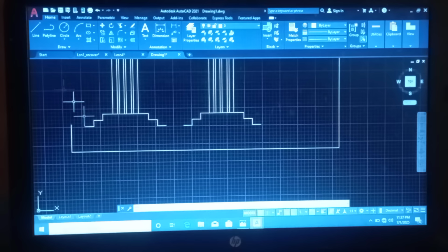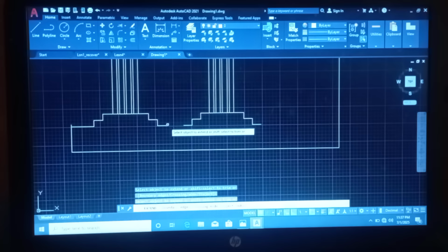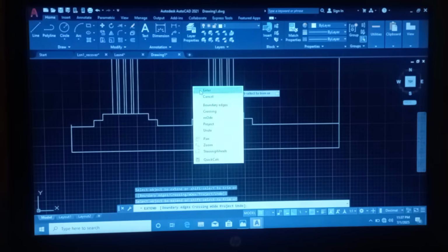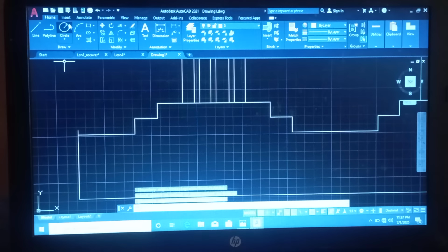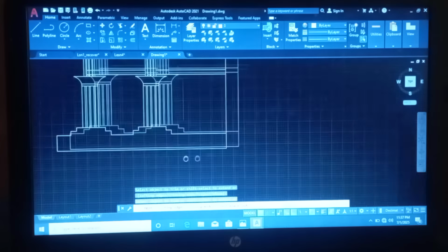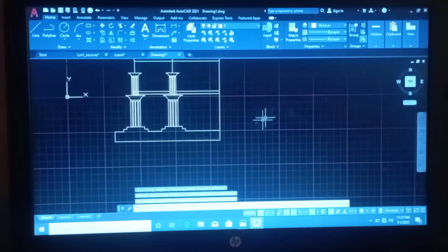There are many ways of going about it. Instead of taking line to come and draw, I come to modify, use extend. Watch what happened now. We extend it automatically. See what happened. Extending. Watch the left side, the right side. It extends and does that. So I'm using extend tools, which also can be found in the same place with trim. This place is rough and can get it up. So it's taking the shape gradually, right?